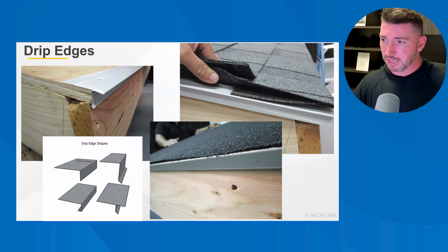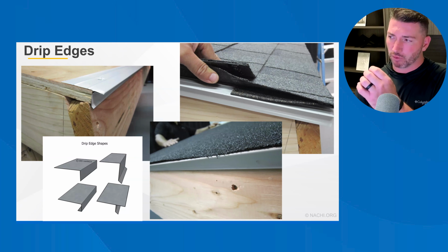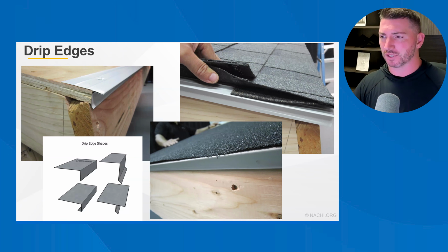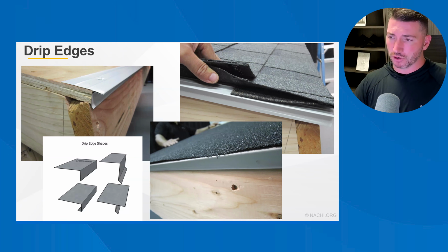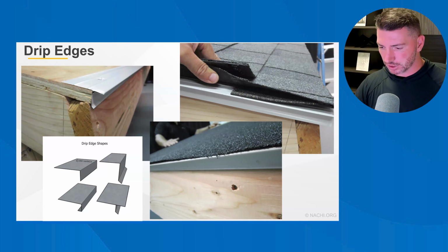As you might be able to see, the design for drip edge is really primarily to protect the plywood sheathing because you want to create a situation where the water that's slowly dripping off the roof does have a tendency to run back underneath the surface of the shingle. And if there's no drip edge there, that water will touch the plywood and the plywood will wick it up, eventually will rot out and will create leak issues.